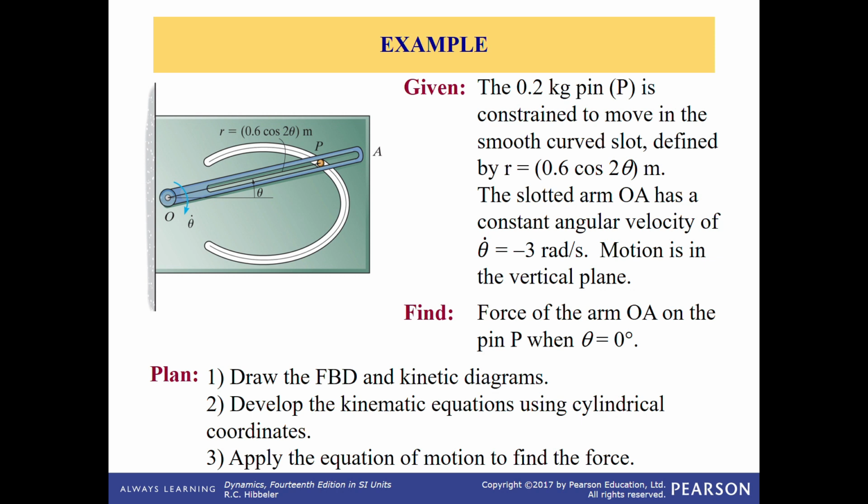And then you also need to draw the kinetic diagram to show the motion of the particle. Next, develop the kinematic equations using cylindrical coordinates. This one is related to Newton's second law of motion, summation of F equals ma. So you need to identify in which direction we have the acceleration. Then next, apply the equation of motion to find the force.